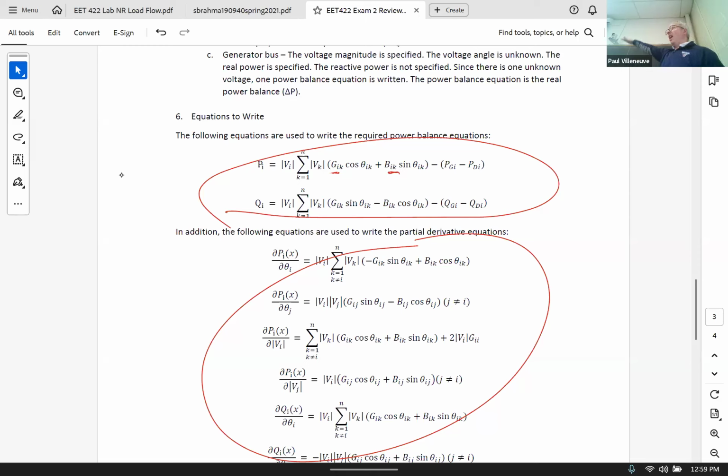If you recall, we derived those in such a way so that we split up the P and the Q, so that all the real parts ended up in the P and all the reactive parts ended up in the Q. So we've already sort of equated each of those to make sure all the J terms are gone. No J terms whatsoever.